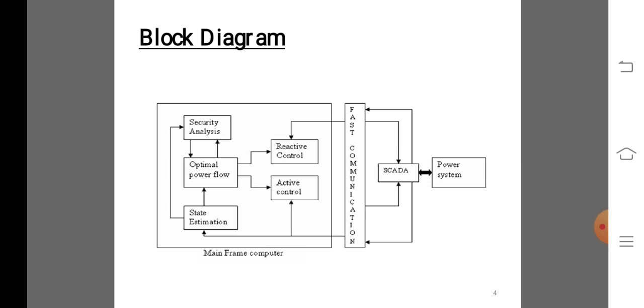It has some levels to control the energy center. That's our turbine governor, adjusting generation to balance changing load, instantaneous control. Second one is AGC, called load frequency control. We have seen this in the third note of power system operation and control. So AGC maintains frequency and net power interchange. Economic dispatch control distributes the load among the units such that fuel cost is minimum.